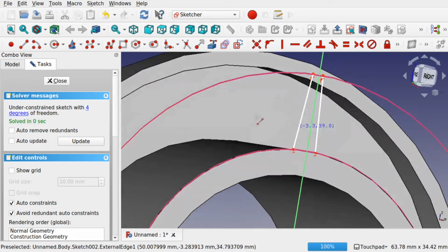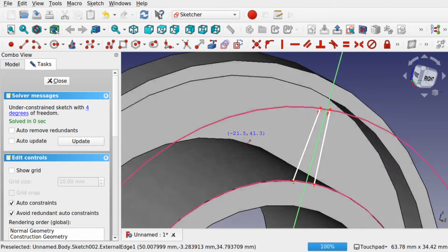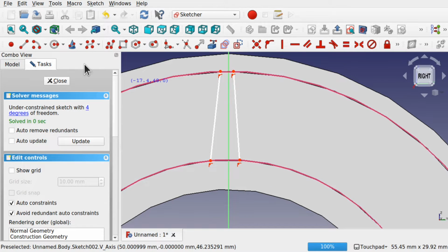So we're looking to pad this and bring it up from here. This is invalid geometry at the moment because it's not closed, so I'm going to use the endpoint and rim point arc. So we can auto constraint to this point here, auto constraint to this point here, and create our arc. I'm just going to bring this up. Make sure you don't hover over this line because it will create a tangency against there, which we don't want. So just put it to the side.